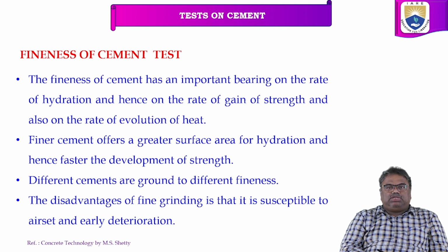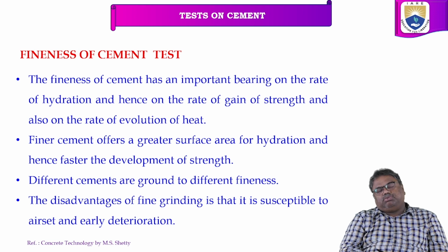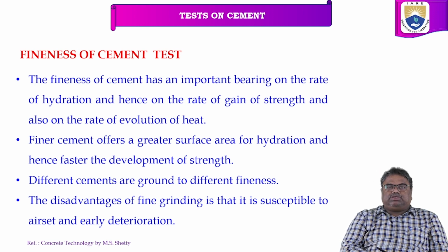The disadvantage of fine grinding is that the cement is susceptible to air set and early deterioration. So this is the only disadvantage of the cement if it has very, very fine grinding. So we should have some value, right? Those values as per the recommendations, we need to test it, right?